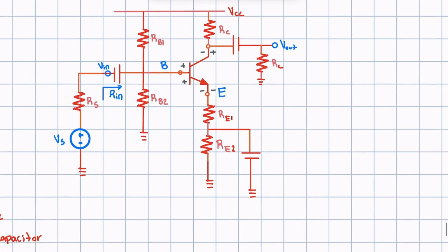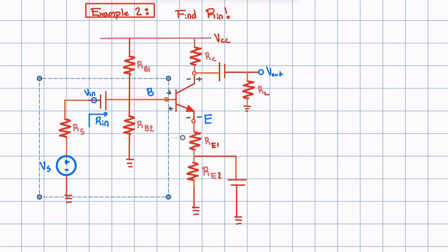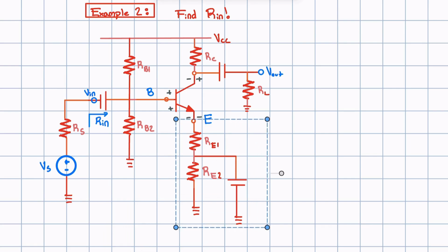The second thing is that we have our input signal, Vs, down here. And this input signal is going to implicate a current direction, but it also means that we're not going to multiply anything in the base by a constant because it is directly in series or parallel to this Vs. Everything after R pi would be multiplied by a constant of 1 plus beta.